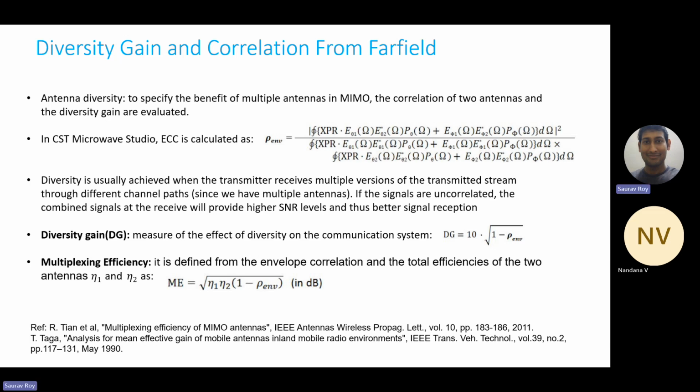Now, microwave has a wavelength of, at 4 gigahertz, around 30 by 4, around 7.5 centimeter. So obviously our absorbing surface, or whatever surface we keep, should have irregularities of more than that. Then only it will not let it reflect.